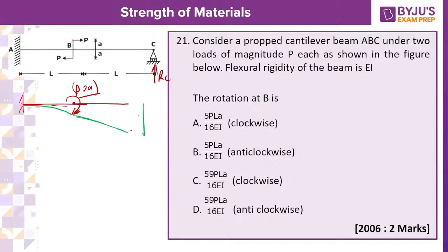So the downward deflection you will be getting only due to the moment, that you need to calculate, and there also this deflection is due to the moment, which is length L. So the deflection is ML square by 2EI, and here the deflection will be L theta. These two I will be adding here. That is the downward one.